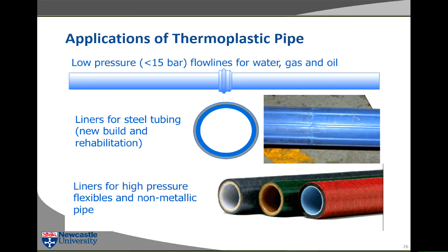So take the example again that I said of a steel pipe. If you had something which is very corrosive in the steel pipe, most often in the oil and gas industry, it's injection water, because injection water contains a lot of oxygen, and it also contains various dissolved salts, most of which are corrosive to steel.